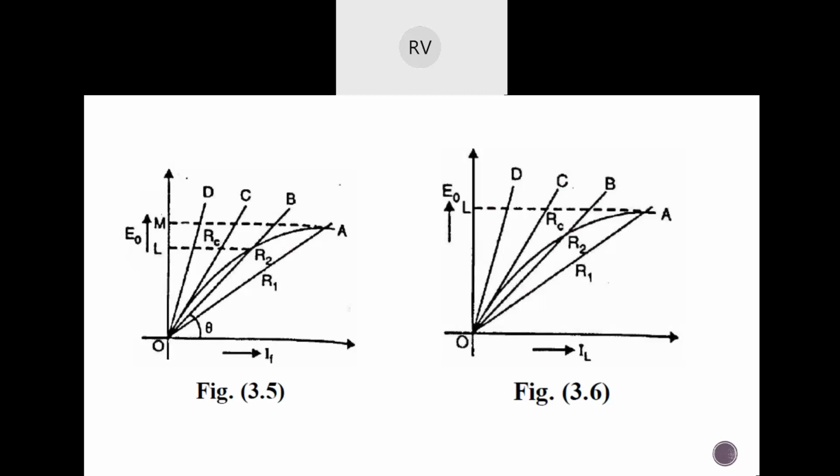And after drawing the magnetization curve, we are going to find out the tangent, at which point the tangent is drawn. Okay, this tangent should always be drawn from the origin, and it should meet the curve. Tangent means it should meet the curve only at one point, right?